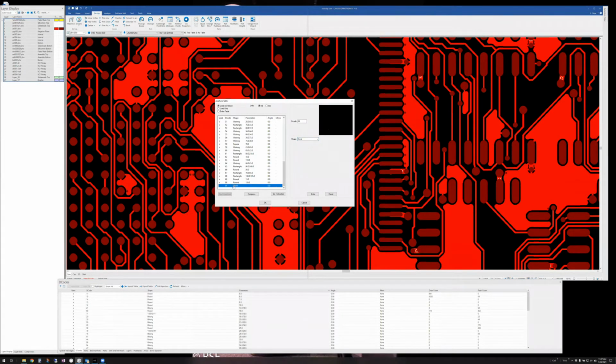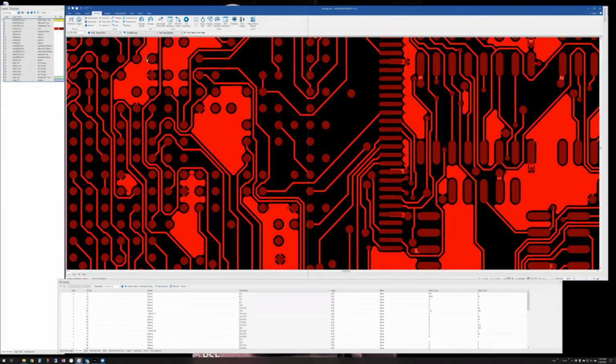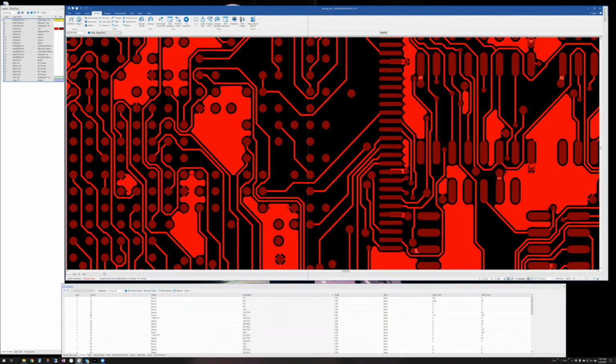So now I'm going to go in here and redefine a new aperture that is a round 27, hit enter and OK, so that now when I go out and I say change decode, first of all, always pay attention to what the software is looking for here. So select a single item, or W for group. Well, if I just want to select one item, I just select it, and then right button to change, and I'm given the decode list, and I pick the decode that I want to change it to, and it changes it.